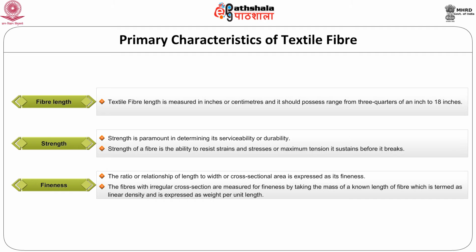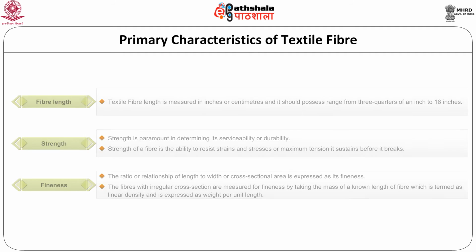In case of coarse fibers, the length is 700 times more than the width. For very fine fibers, the ratio is up to 1:5000. Usually, fine textile fibers can produce fine yarn and fine fabrics. Fiber properties, characteristics, and end uses are determined by the fiber fineness.